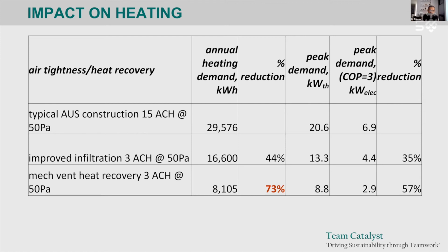Now, one of the things that we've been trying to tell clients, very difficult to get them to understand, is that you can actually undersize your system slightly, so that on the hottest day when it's 36 degrees outside, you don't need to be 24 degrees exactly on the inside. You could be 26 or 27 and that'll still work, okay? And that kind of thing you can test on a model.